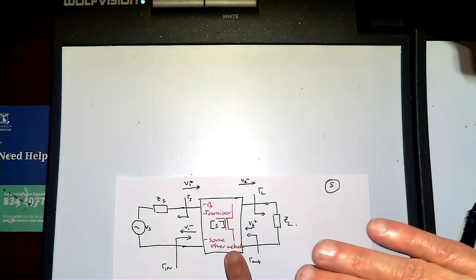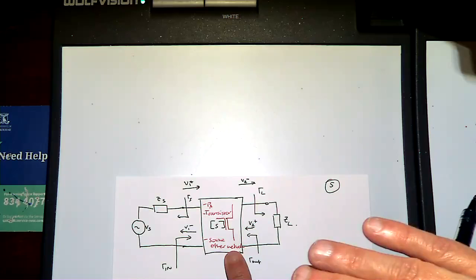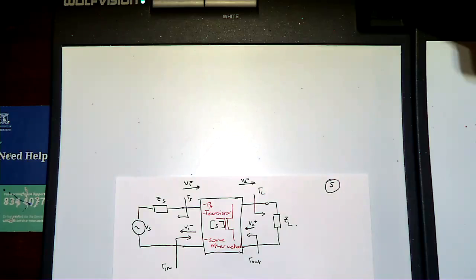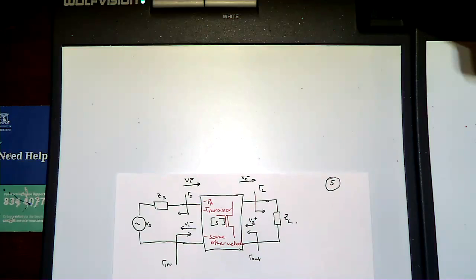Generally, the load impedance. Sorry? The load impedance. I mean, that's if you're conjugately matching, but generally you want low output impedance, right? So you want high input impedance, so therefore you don't suck any current, and low output impedance, so therefore you can suck as much current as you want without increasing the voltage, right? That's what you do when you're doing DC circuit design, in very low frequencies, right?